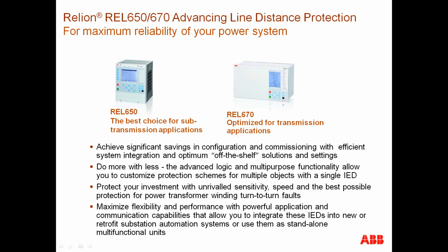SOTF, where you want to apply it is where the voltage is at zero and when you're energizing a dead line. So you want to make sure there's no fault on that line, and you expect that voltage to come back within a cycle. And if it doesn't come back, then you trip it.